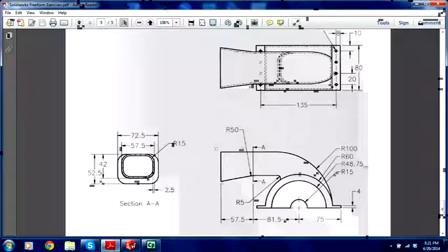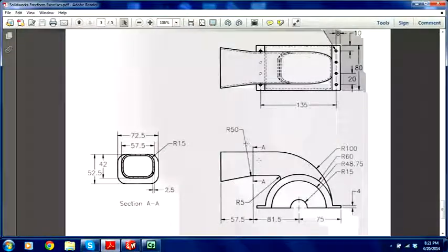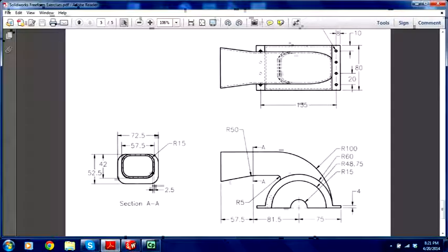That's going to be a loft, and then you have the section that connects the outlet to the main section, which is all the sheet metal. So you have the semicircle 1, the outlet 2, and then this middle section that connects it. And then we're going to have to somehow shell it, and then add the 8 holes. The first thing we should draw is this semicircle.